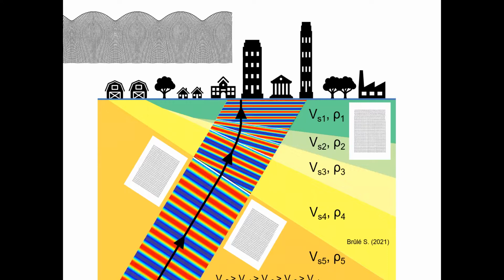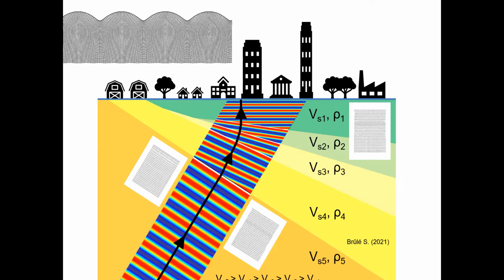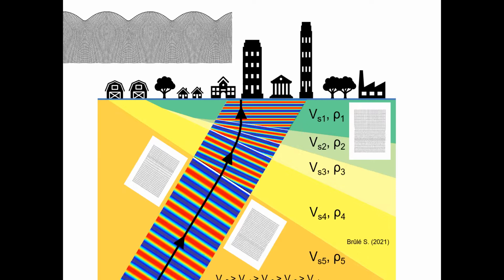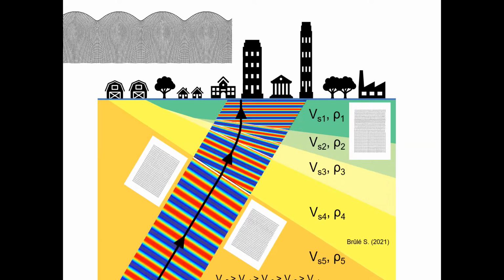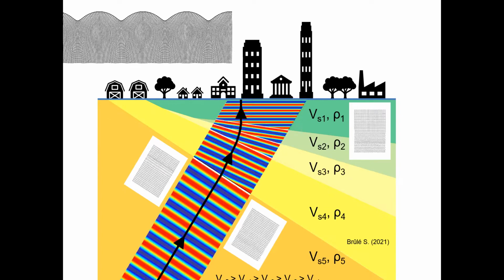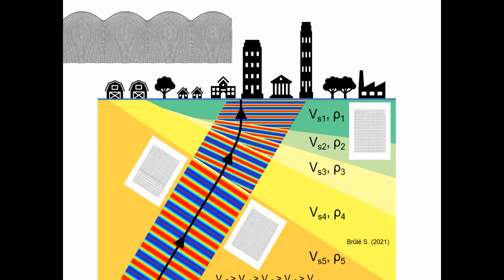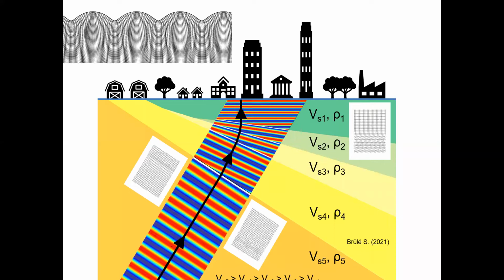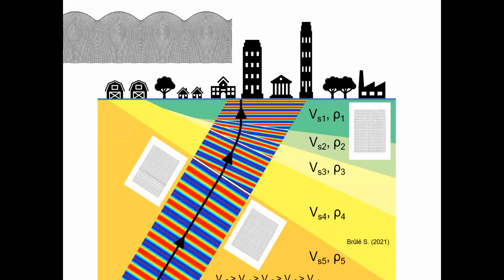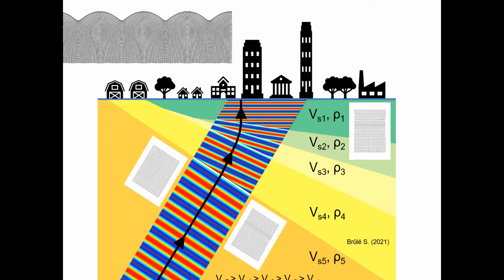The building is resistant for the reference earthquake, but sometimes we have too important a drift, the displacement between two floors, which can create a bad feeling inside the building. So sometimes the tuned mass damper is also used for the feeling inside, the seasickness. Not only, but it can reduce the displacement of the building.